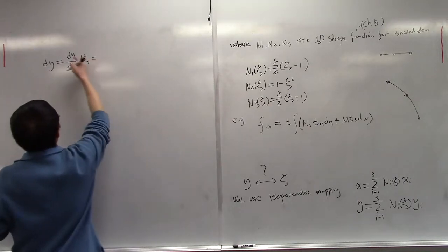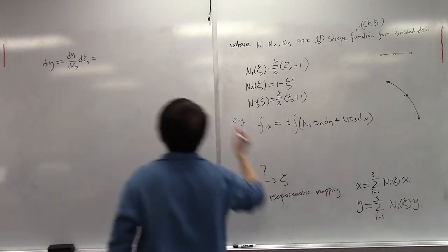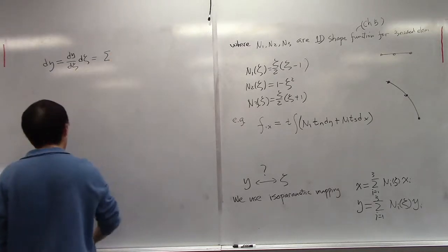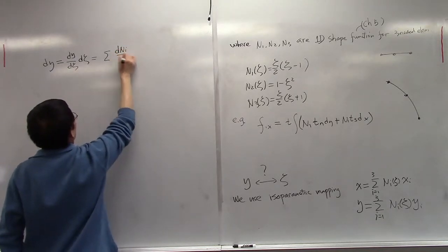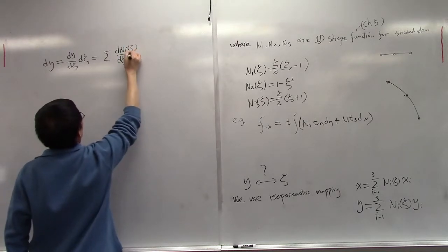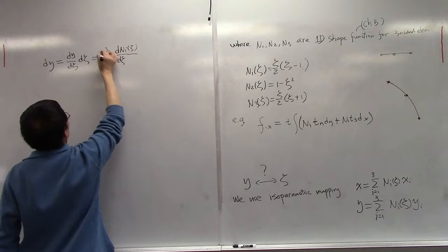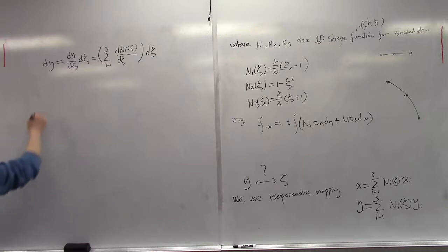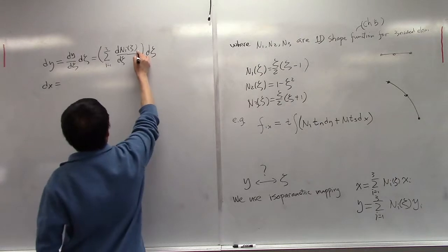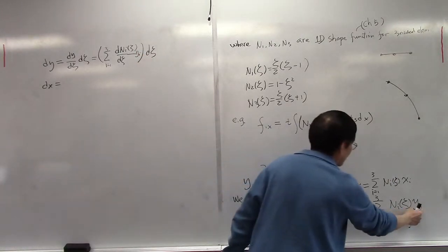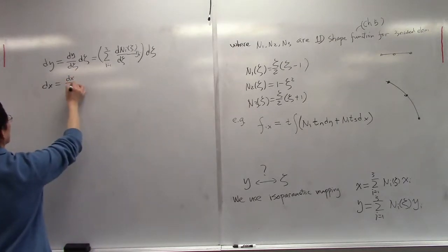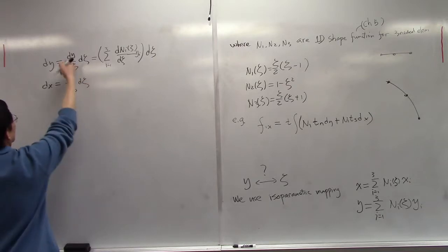And with that, dy/d theta, put this in. Now we can say dNi, differentiation of Ni with theta, and I from 1 to 3, all these together, and then d theta. Right? And dx, times yi. Don't forget that. We have yi here, and then this will be dx/d theta again. This is the chain rule.